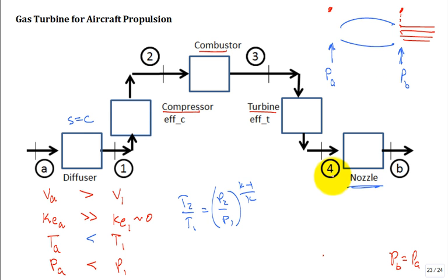But for this nozzle, what about the pressure to feed the nozzle? Should that be higher, equal to, or less than the pressure at the exit of the nozzle for a good nozzle? Greater. What about the temperature compared to the temperature at the exit? Greater, equal to, less? It's going to be hot and high pressure. Feed hot, high pressure to the nozzle.